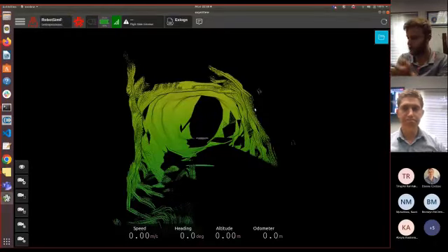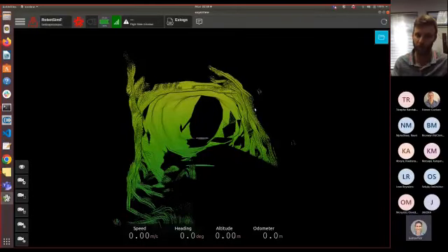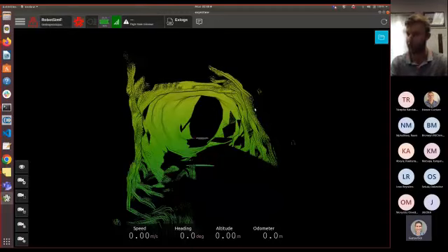Joel, yes. So a room and pillar mine is a perfect example of an explorer. It generates a full flight path on its own, and it'll go around those pillars fully on its own. You don't need to give it a direct flight path. You don't need to say, hey, go behind this pillar. It's going to go all around every single pillar and generate a scan entirely of the room and pillar area that you're in. So it generates its full flight path solely based on that volume I gave it. That's where the autonomy comes in.